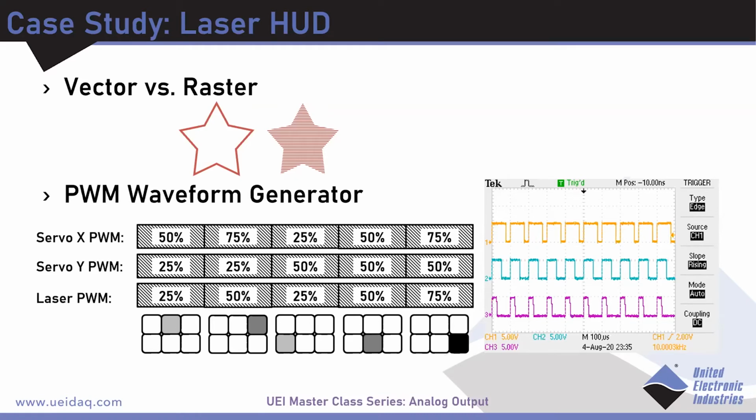Now, what that's leading us to is that our 364 waveform generator can natively support these kinds of waves. We actually have a built-in pulse mode. On this oscilloscope capture on the right, which I took earlier in the week, you can see duty cycles natively from the 364 that you might use to theoretically control this X and Y servo.